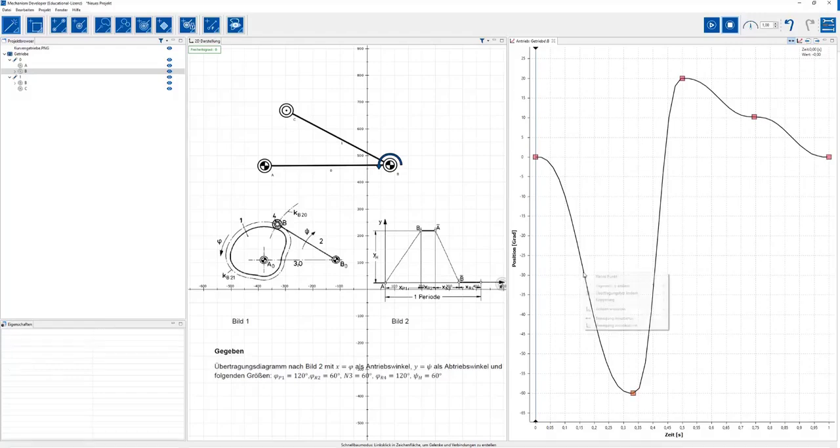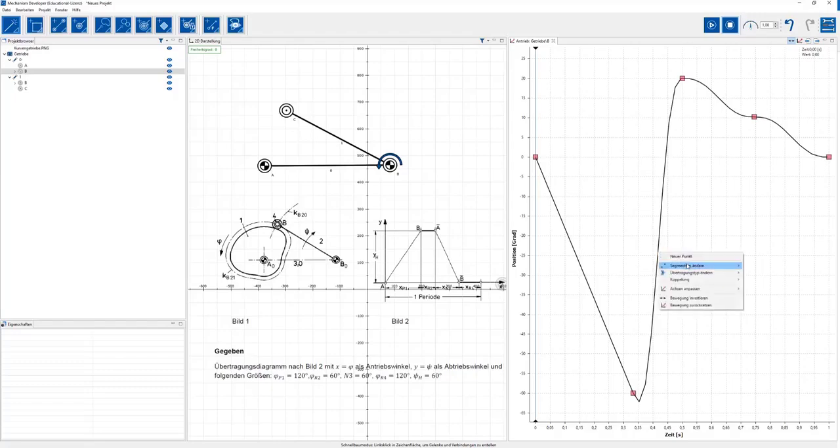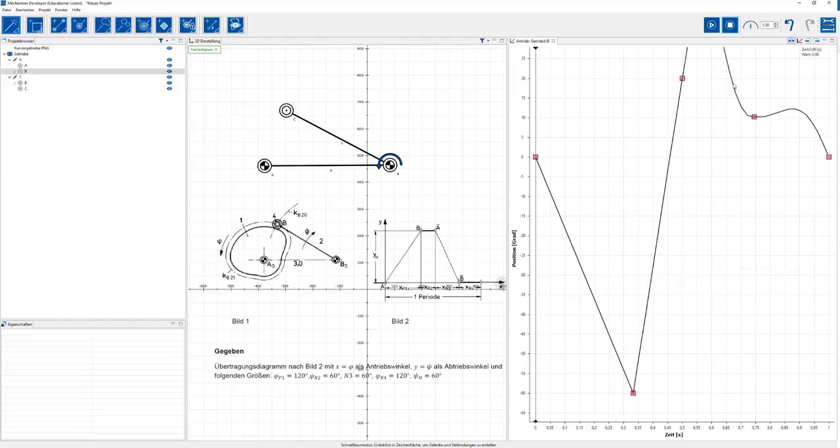Now, what I still want to do, I'll undo that. For now, I want to define straight lines, so a line, a line, a line. I want the segments to be connected only by lines. Line here as well. And this segment also as a line. Now this point has reached the top, but I don't want it here. I want it at 0.5, which is correct because that corresponds to 180 degrees. But in this region we are also still at negative 60 degrees.